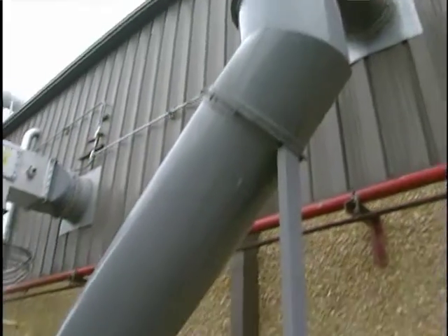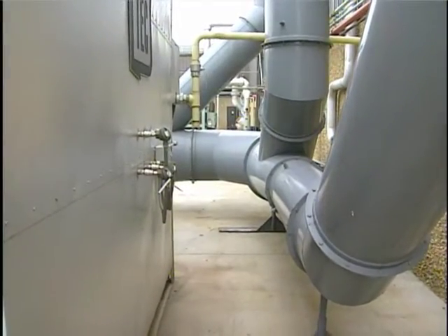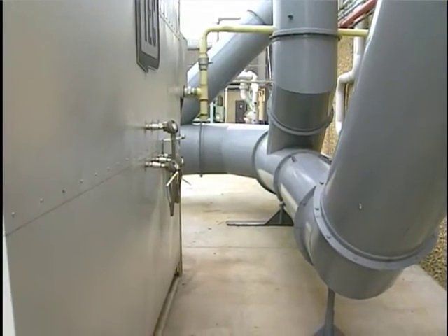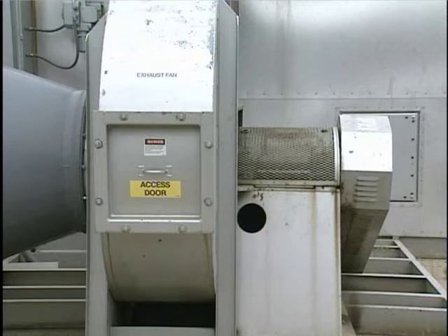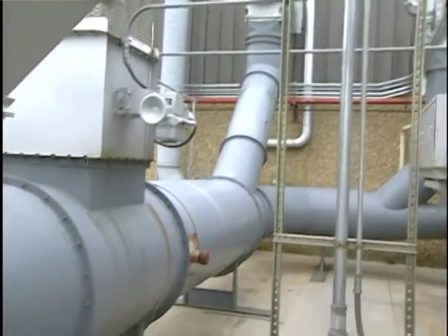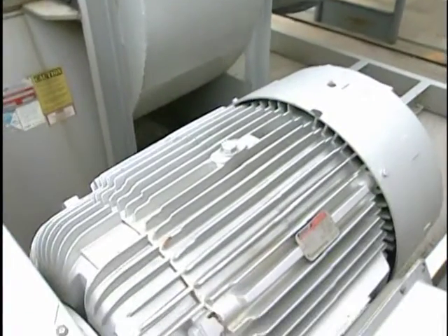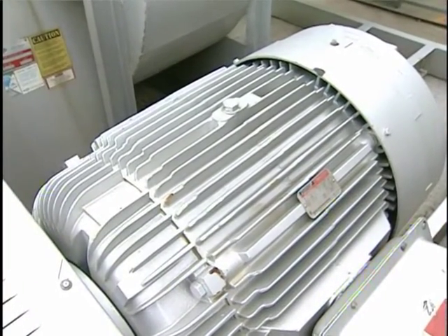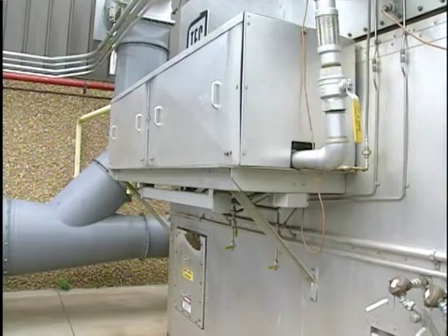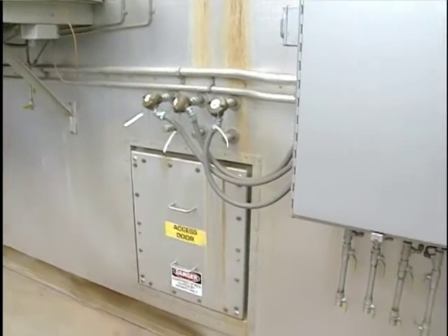Decreased gas flow rates will result in reduced capture of the contaminants at the source, resulting in fugitive emissions. A decrease in the gas flow rate is indicated by decreased fan motor currents and decreased hood static pressure. Increased gas flow rates will shorten the residence times in the incinerator, reducing destruction efficiency. An increase in the gas flow rate is indicated by increased fan motor current and increased hood static pressure.